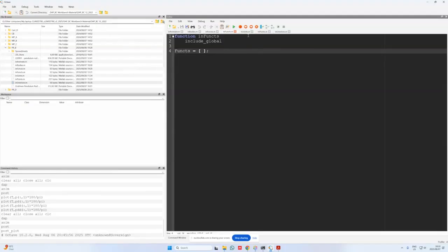And then I believe the last or second last input file that we have to consider is inUvectors. In this case, you'll notice inUvectors is also an empty list. The reason for that is we don't have any translational joints. Whenever we start specifying translational joints, we're going to start setting up unit vectors, and this is where inUvectors is going to become important. However, for our undriven pendulum rod, our single joint is a revolute joint. We don't have to worry about translational joints or unit vectors, so we leave the Uvectors list as an open list.